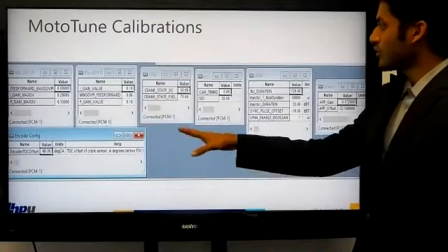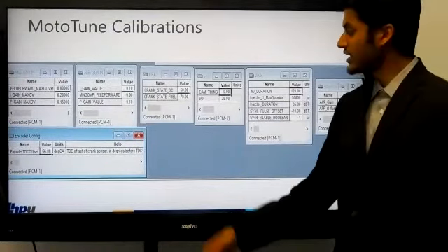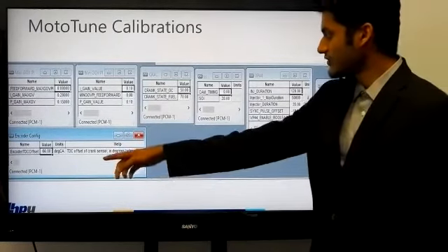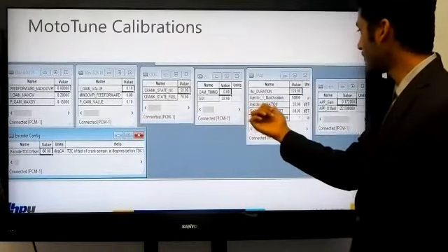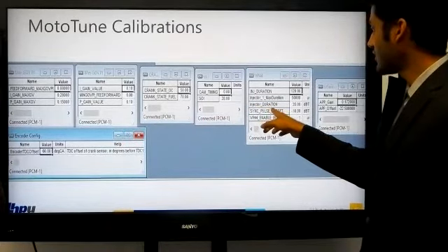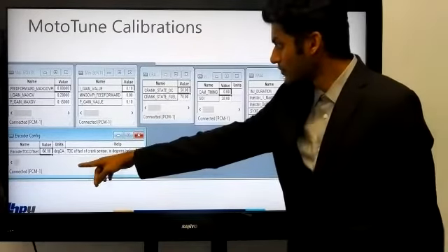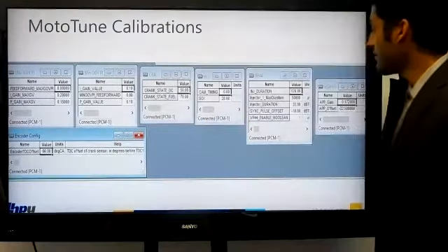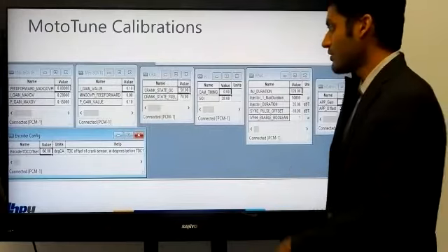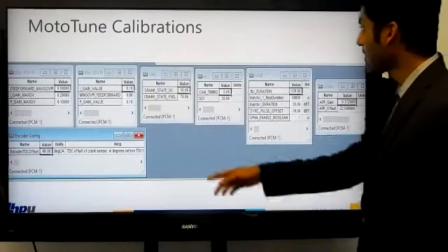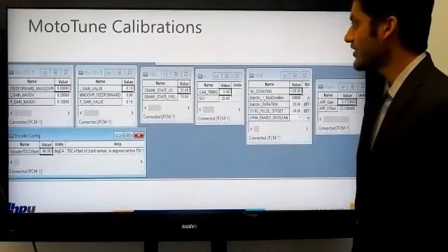So these are the important motor tune calibrations we made while running the engine. Encoder TDC offset and the injector offset duration. This is offset duration, sorry for the mistake, I gave the wrong name. These 2 were the important parameters to synchronize our pulse with the Cummins reference pulse. And we gave a crank state fuel of 70.